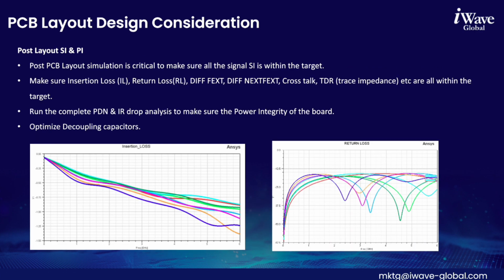Finally, once the layout is done, we have to do the complete post-layout simulation to make sure the insertion loss, return loss, differential crosstalk, near-end crosstalk, far-end crosstalk, and trace impedance are all within target. We also do PDN and IR drop analysis to make sure of the power integrity of the board, and if needed, do decoupling capacitor optimization in the post-layout.